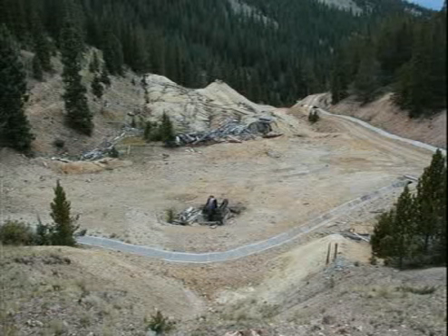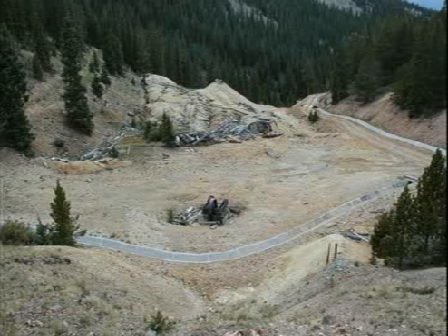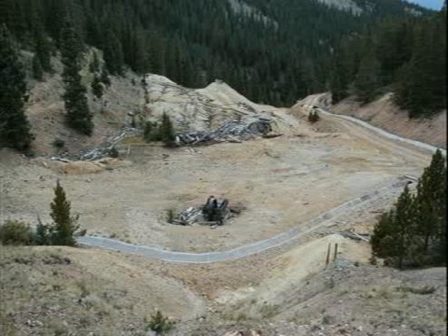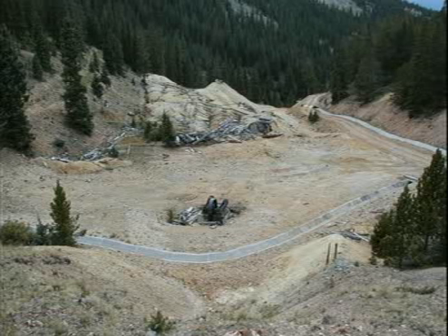Like all ditches, it's going to need some occasional clearing. It's going to need some maintenance, but it's pretty good and it could last for quite a while. The concrete itself, in acid cases, can prevent some acidification because it dissolves and it can neutralize some of the acid waters.